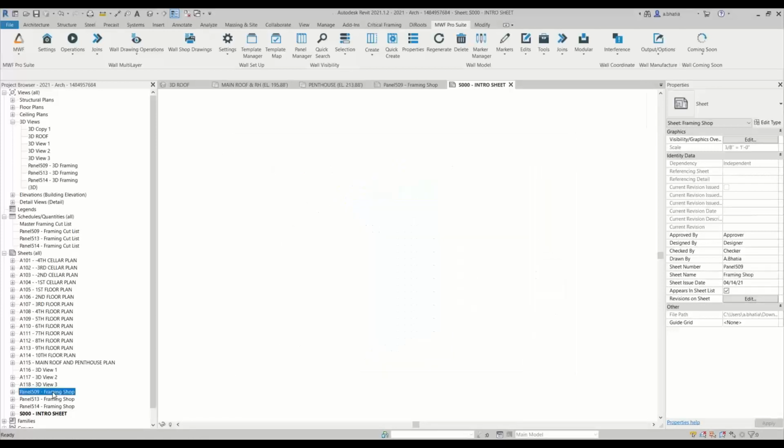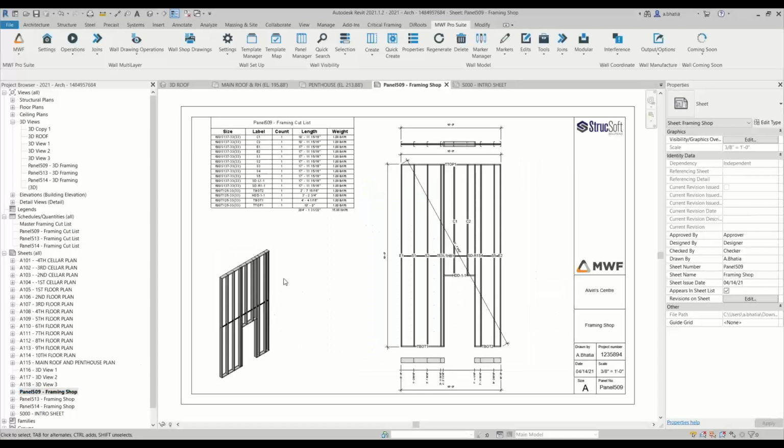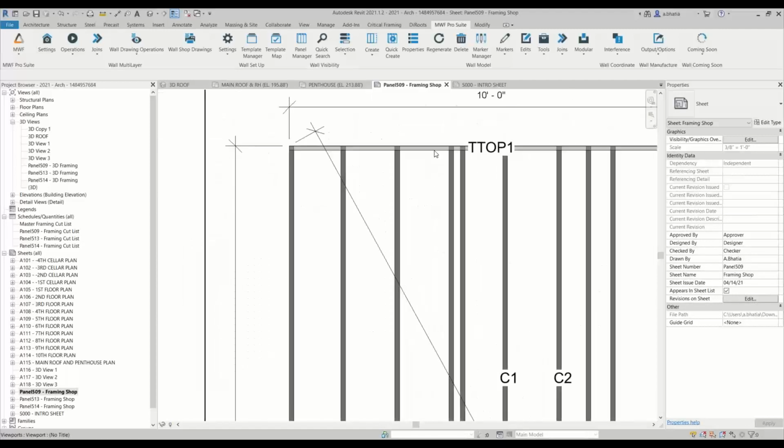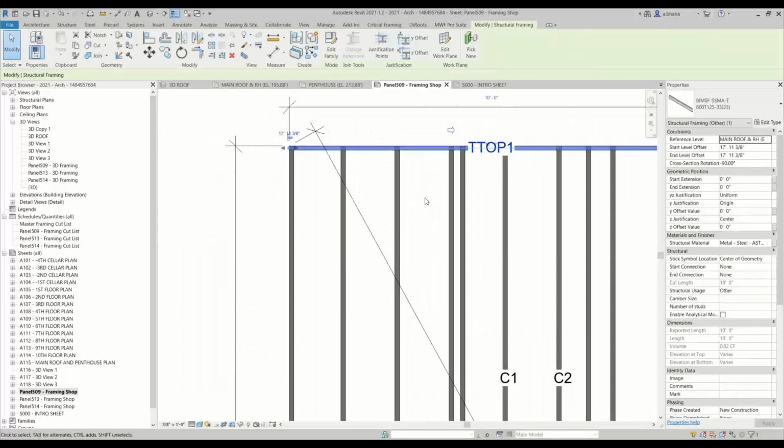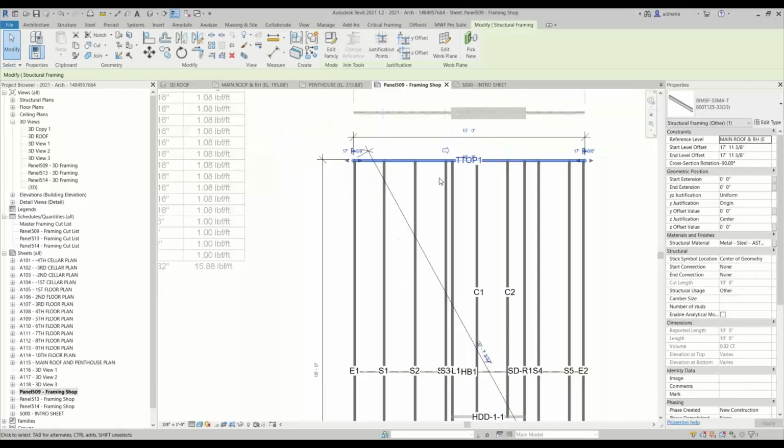So what are shared parameters? Well, technically, what are parameters, right? Parameters store information, like if I want to tell you that this is a track, I will store that information in it. Everything from the name of the family to the type of the family to the category is a parameter. So there are a few types of parameters within Revit.